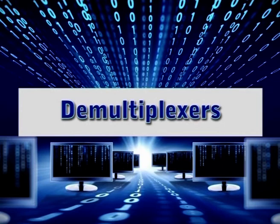So, now we will study another combinational circuit called demultiplexers. A demultiplexer, also called demux, performs the reverse operation of a multiplexer, that is, it receives one input and distributes it over several outputs. It has only one input, n outputs, and m select inputs, where m is equal to log n. At a time, only one output line is selected by the select lines and the input is transmitted to the selected output line. A demultiplexer is equivalent to a single pole multiple way switch.